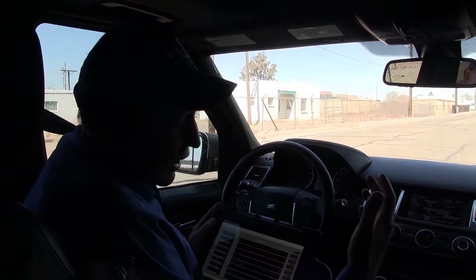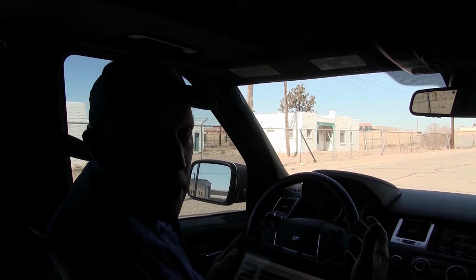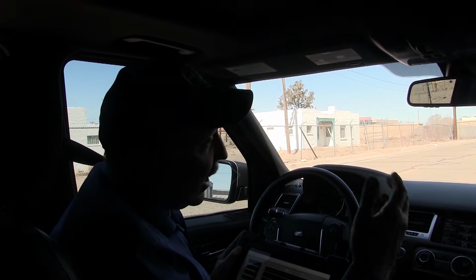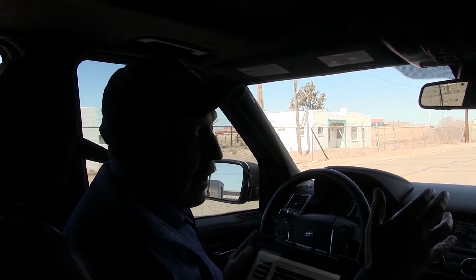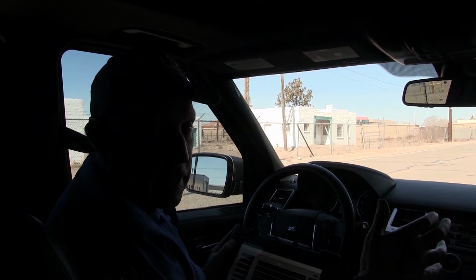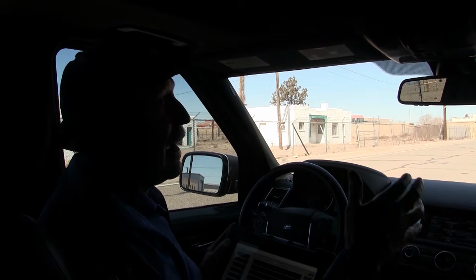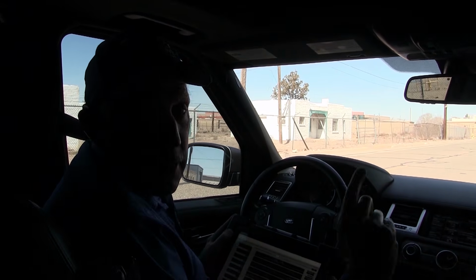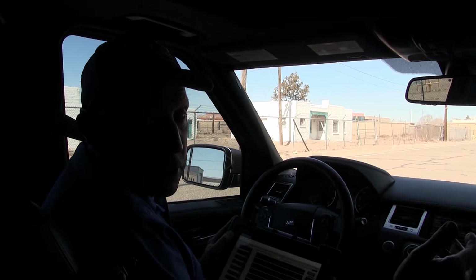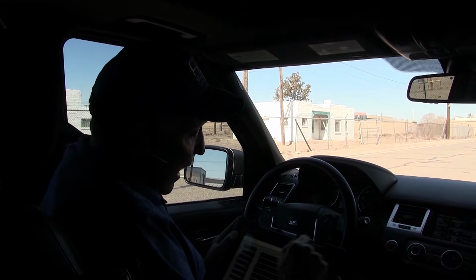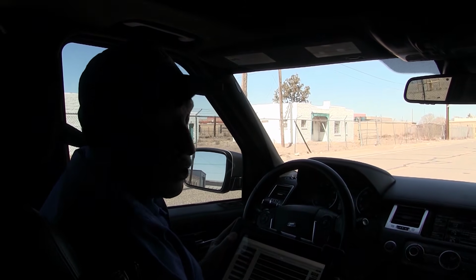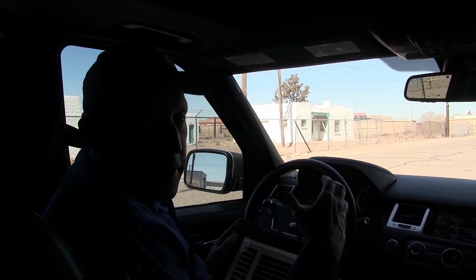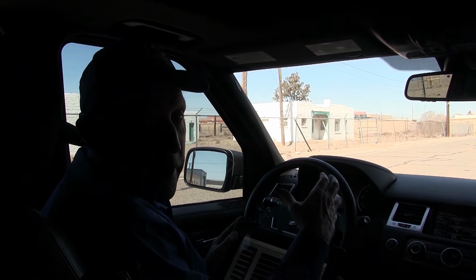Now guys, that is a huge test for me, because now I know that the whole feedback system works. The O2s, the MAFs, whatever, all of that's going to work. And then the computer could see that data and it corrected it correctly. It made the right correction because what came out the tailpipe stayed at a lambda of 1. It was 1.02, that's a 2% change. But I had almost a 50% change in fuel trims. So whatever the problem is, we now know that it's not air-based because the mass air sensor read correctly.